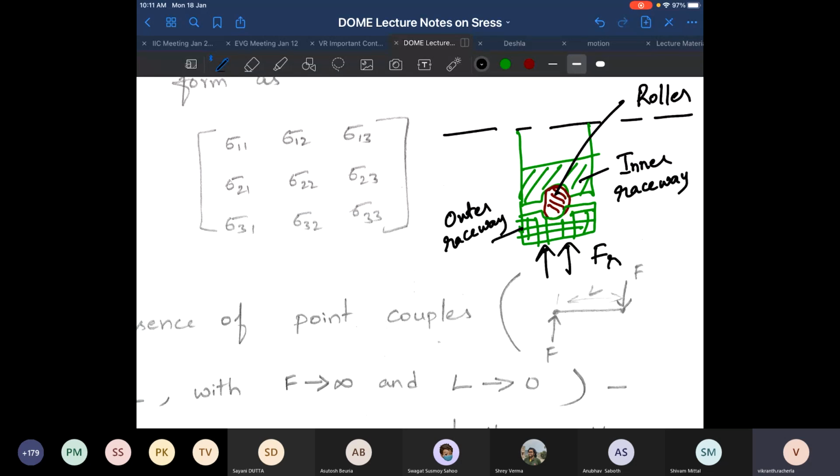You have this piece of information. But in reality, the machine elements will be subjected to a complex three-dimensional state of stress. So one big question is, how do you use this information which is being obtained in experiments for some simple loadings like tension or compression, and extrapolate it to a more complex situation? That is where the failure models or the mathematical models come into picture. They help you do this extrapolation.